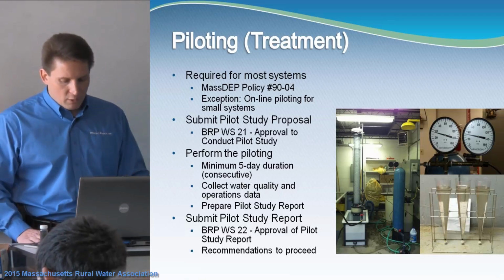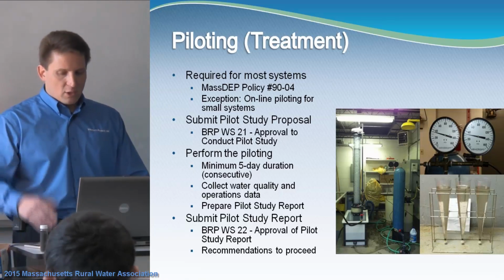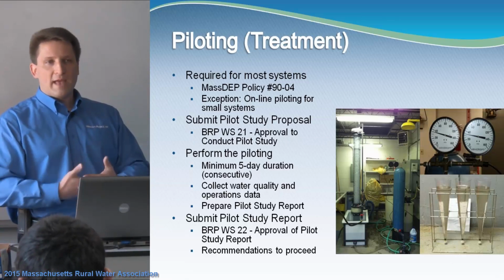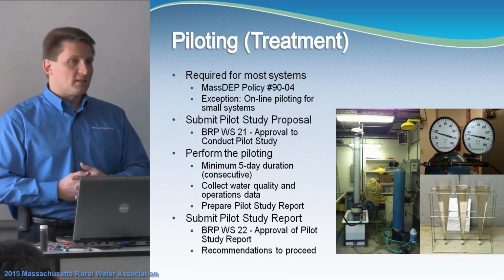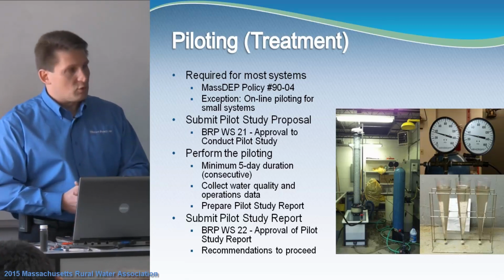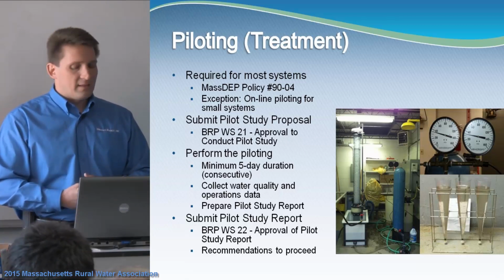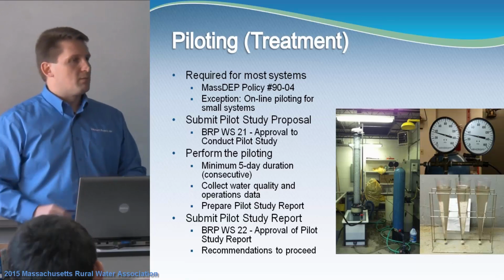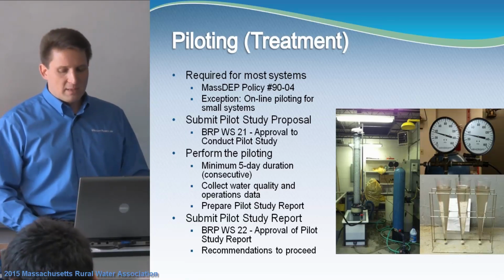And then the bottom right photo, that's actually 3 Imhoff cones. You typically use these just to measure how much sludge you have in your backwash and how quickly it'll settle. And the Littleton wells, they didn't have too much iron or manganese. They had just enough that they wanted to remove it, but you can see a couple of brown dots at the bottom, so it was pretty minimal in regards to the sludge for a typical backwash.